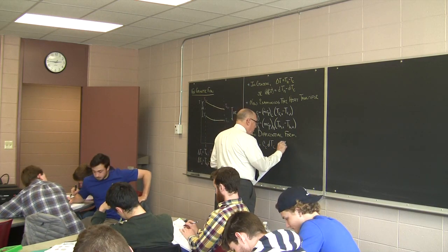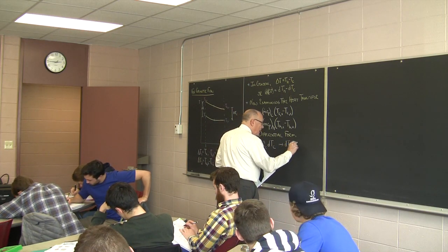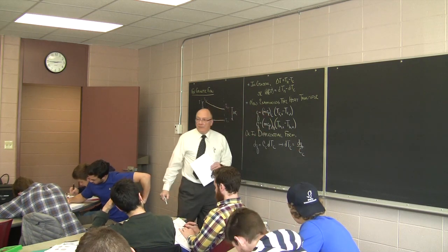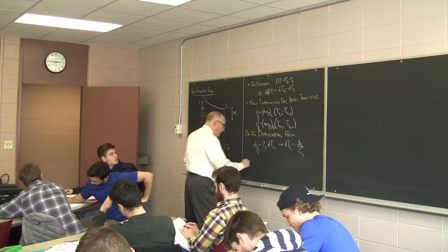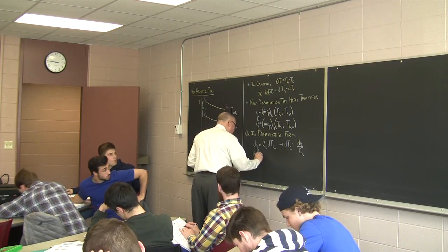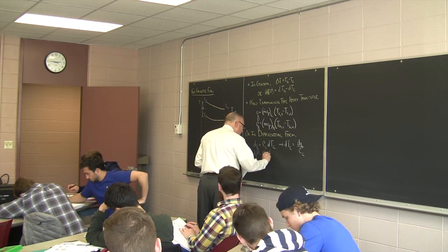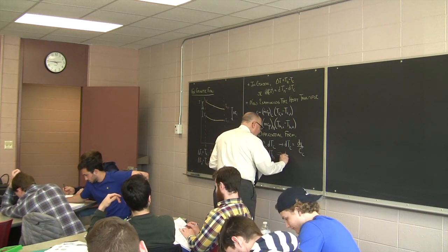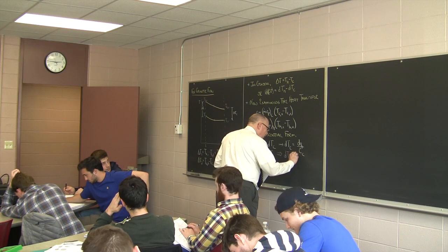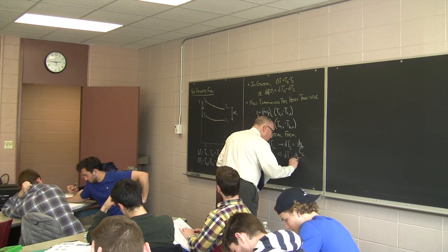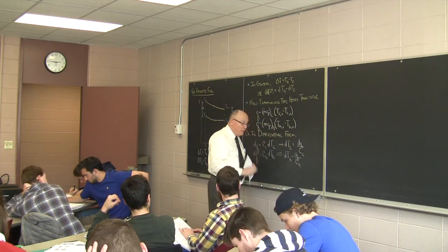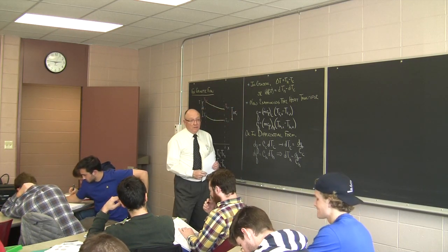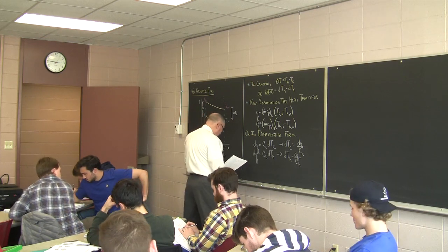Or we can rewrite this as dT_C is equal to dQ over C_C. And similarly, dQ for the hot fluid is going to be equal to C_H times the differential change in the hot temperature. Or we can say dT_H is equal to dQ over C_H. Keep in mind that these dQs are identical, okay? The heat given up by one is the heat gained by the other.